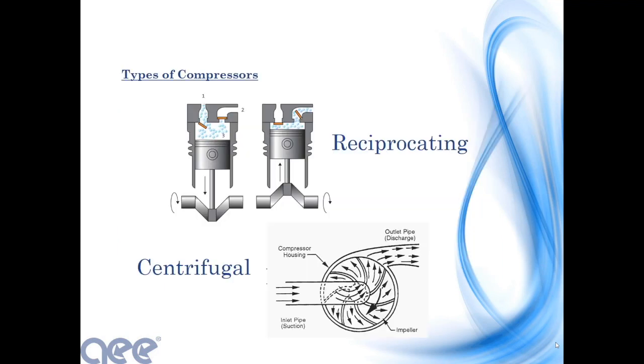Now when you look at a water-cooled chiller, there are basically four types of compressors. There's reciprocating, centrifugal, scroll, and screw. All those mean is there are different ways to compress refrigerant gas from one state into another. In a reciprocating chiller, it's essentially just piston technology.